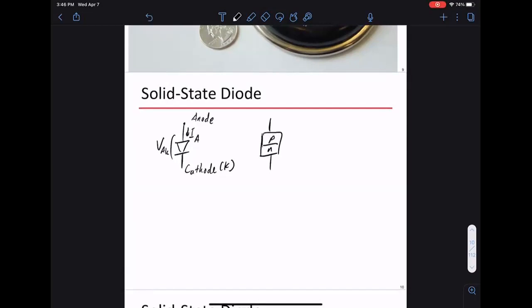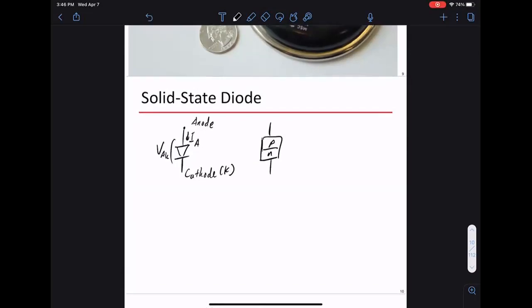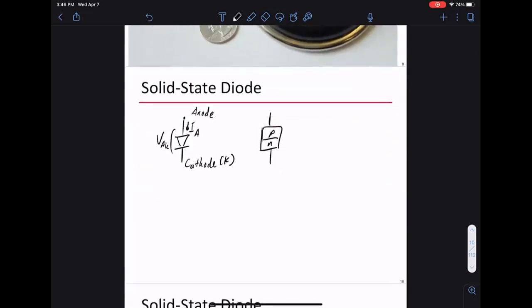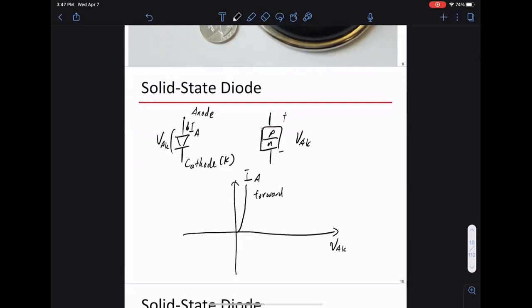So what this p-n junction allows us to do is basically, if you look at the voltage measured with this polarity, what happens is you look at the current versus voltage, this VI curve. Then in the forward bias region, you need a little bit of voltage difference, then this shoots up really quickly. Right? This is called the forward bias.